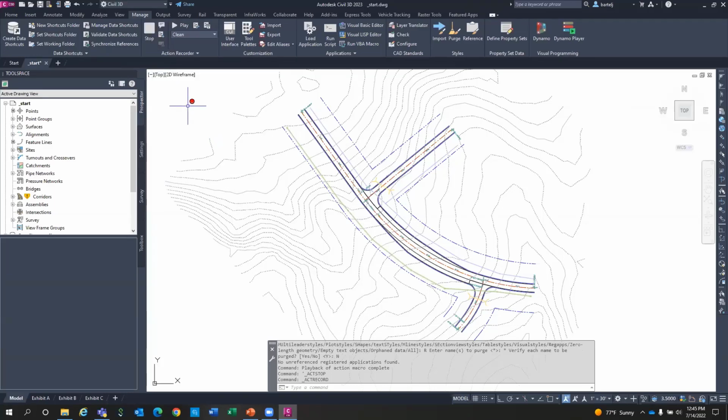We'll go to record. And we'll say, in this case, because I'm going to start stringing together more and more commands, a good practice that I like to do is I like to start my macros with undo and then M for marker. I like to lay a marker down because if I'm going to be automating a bunch of stuff and if things don't necessarily work out the way that I expected, I could always undo back immediately to that point before that command was run. So that's just a best practice that I like to do when I build these things. So we'll say undo mark. Then what we're going to do is I'm going to go into the command layer.